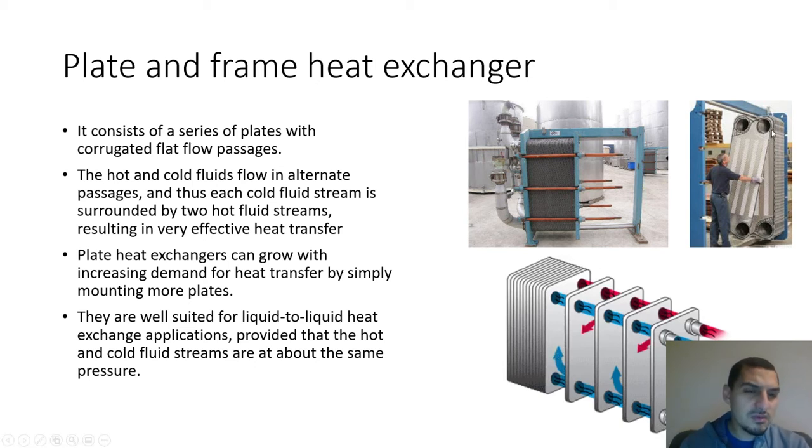Just to understand how it works, because it seems here like a complex or hard to understand figure. So in this figure you can understand how it works. We have some grooves here, and these grooves tell the fluid where it's gonna flow between the plates.